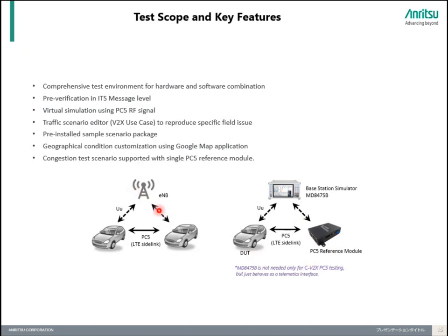And then to simulate the network for UU communication, we have our network simulator MD8475B. Now, if you are interested in solely verifying or validating the PC5 communication, the ITS messages, the CV2X related scenarios, the network simulator is really not required. Just the reference module is sufficient. And if, in addition to CV2X, you do have tests related to UU communication or telematics or basically server communication, that's where a network simulator would be required, otherwise not.